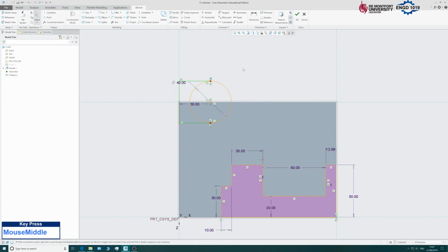And so you can see here there's a bit of an issue with this sketch. So obviously the total outline that we would like is this semicircle, this line, and this line. And so this geometry here is actually confusing the software and not giving us a shaded section. Okay, so what we need to do is basically delete these internal lines. And so we can do that using the delete segment tool. So along the top here.